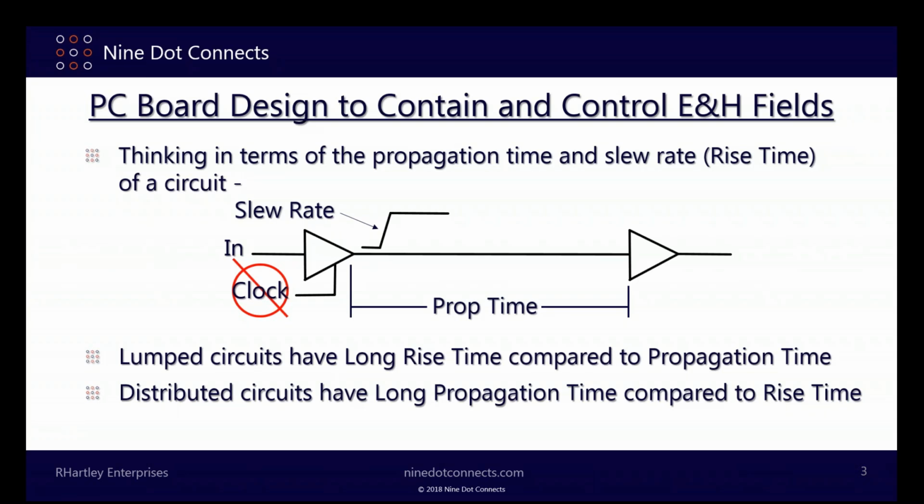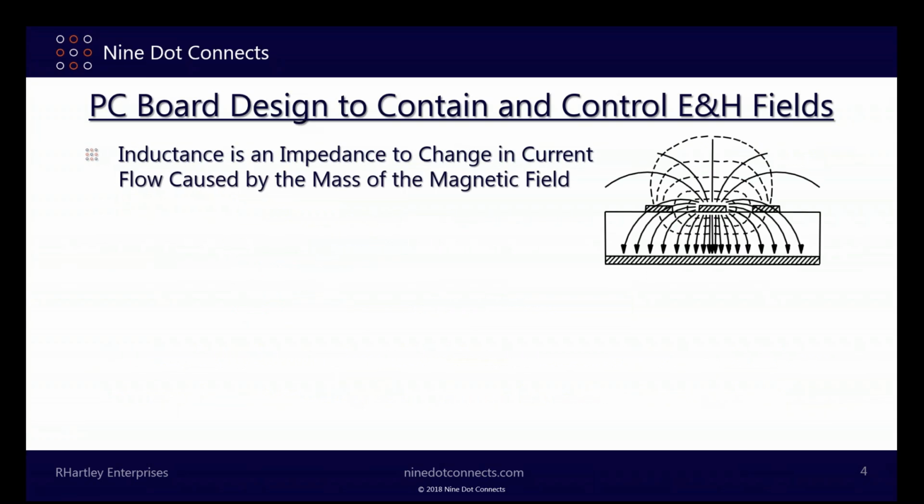Something else to understand that is very important. Everything that goes wrong in a circuit, and I mean everything, all reflections, all crosstalk, all EMI, all power distribution problems, power bus noise, etc. All of these events occur during the rising and falling edge of the signal. Once a signal has gone high or gone back to its low state, nothing goes wrong. It is all about rise and fall time. It all comes down to exactly that.